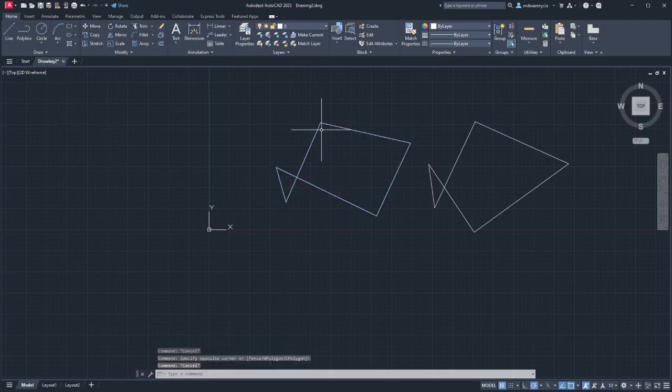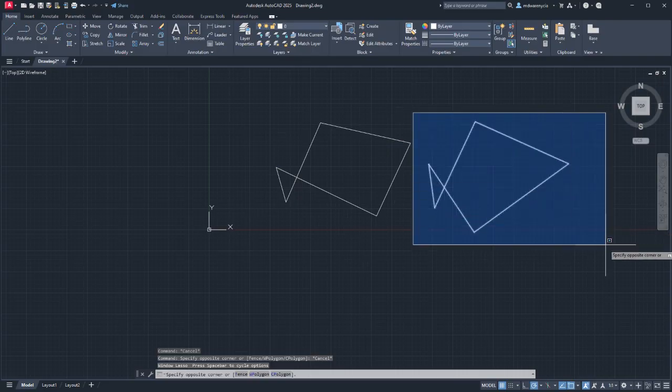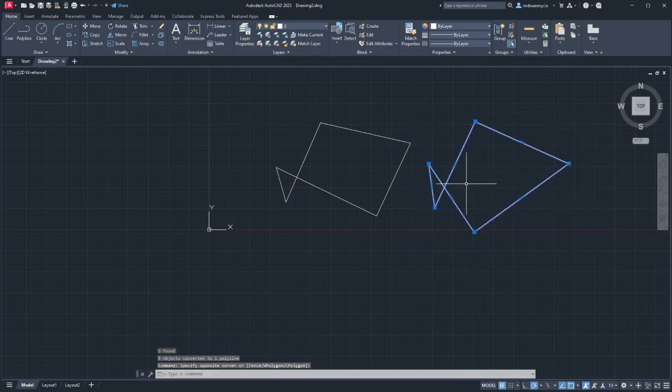All right. So a polyline is just a fancy line. There are some advantages and disadvantages to using both. The main thing I will tell you is that if you have a polyline, you can type explode and it will break this polyline into individual lines. So now there's not really any difference between these two. And if I type, I believe it's join, yeah, then it will basically turn this set of lines into a polyline. So there's times where you want to switch those back and forth. Maybe you want to draw out some part of something with polylines because there are advantages to doing that, and then come back afterward.